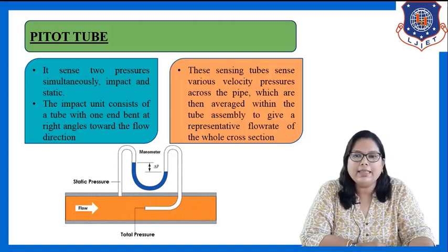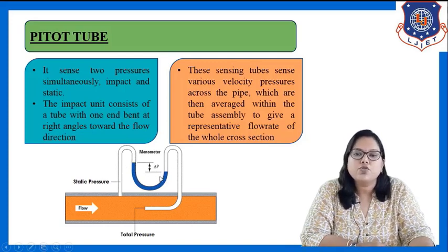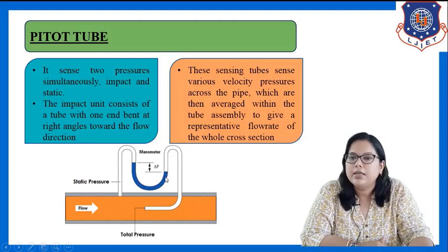And on this other side, we have attached a U-tube manometer. According to the velocity of this fluid, the fluid rises in this tube. According to that pressure, you can see the pressure difference in this U-tube manometer, this blue portion.